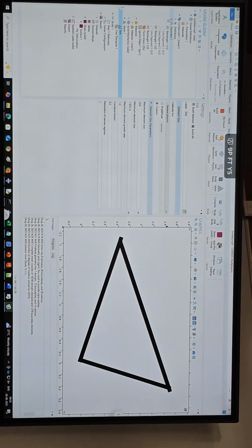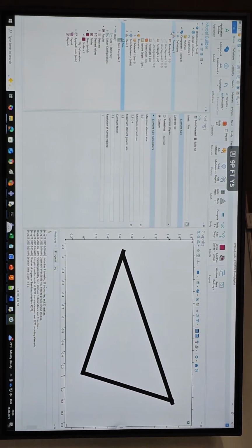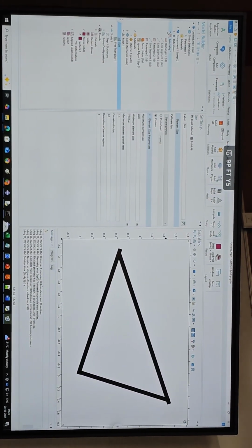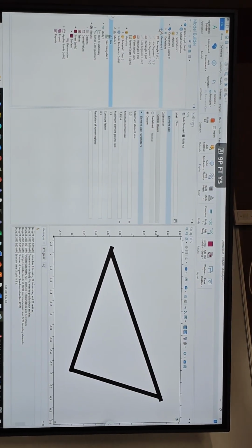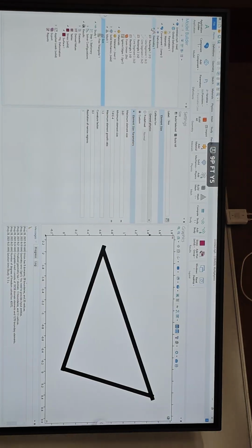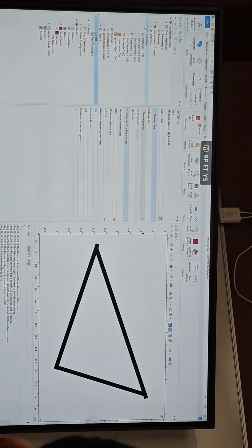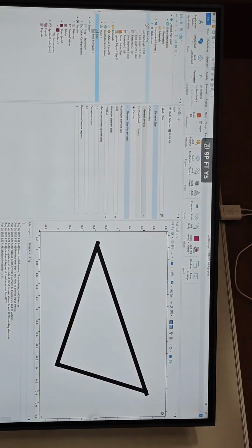Now I'll show you a few other features which can be used. So let's take a step away from this. This is what you'll have to do. This is what Suresh wants you to do. Now we'll also see how we can probe in Comsol. A probe is when I want to take out values from here. So if I'm giving a load, I want to take out a displacement.